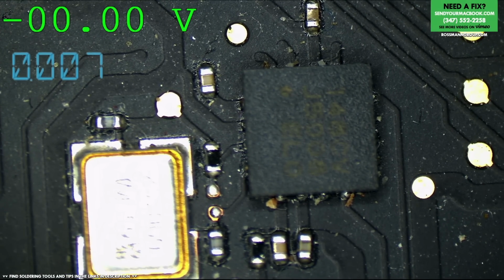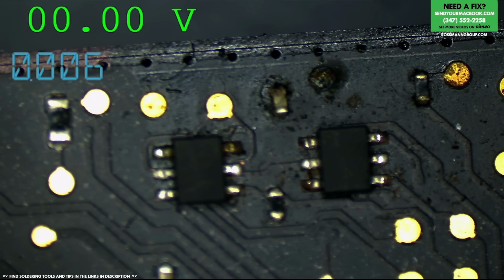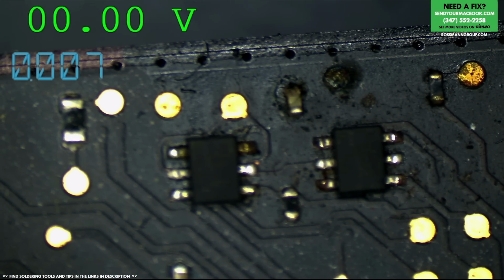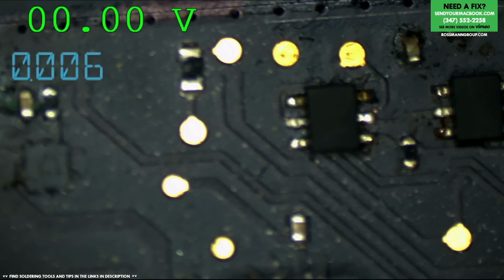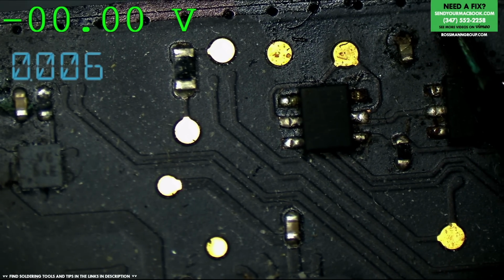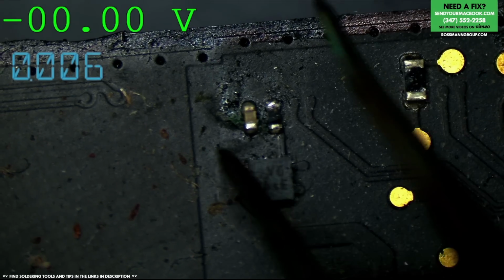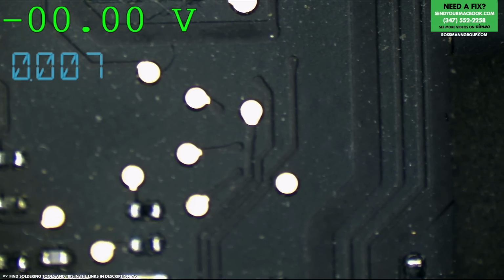Could be it, but doesn't seem to be here. We have a little corrosion on this stuff above it, but that stuff is kind of irrelevant in the grand scheme of things. Those are for JTAG rubbish. Now, when JTAGs are corroded, that can be bad because it'll short things to each other. But over here, nothing is shorted directly to something right next to it, so I'm not necessarily as concerned about that, although we'll come back to the fact that there's holes where probe points should be later.